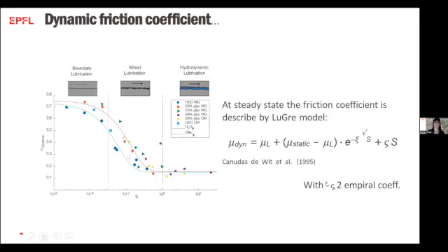And what you see is the dynamic friction coefficient versus the Sommerfeld number for both the Westerly granite samples, that are the diamond, triangle, and square, the purple square, and for the Carrara marble, that are the yellow squares. We ran the tests under dry and water conditions, but here I plotted only the fluid condition, not only water, but only the fluid condition. Otherwise, you cannot plot the dry condition with the Sommerfeld number.